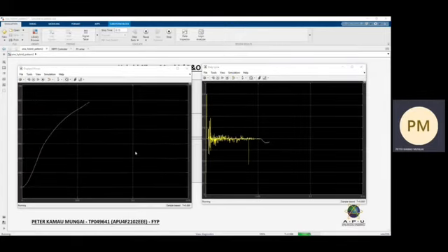So for the given setting, which is a partial shading setting, the system is going to be able to settle at the maximum power point soon. The system roughly takes 5 minutes to locate the maximum power point. And just to provide a working principle, as mentioned, the system consists of two hybridized techniques, which is perturb and observe that tracks the maximum power point by perturbing the operating point, then observing the difference between the power in the perturbations.